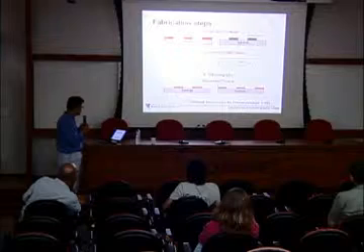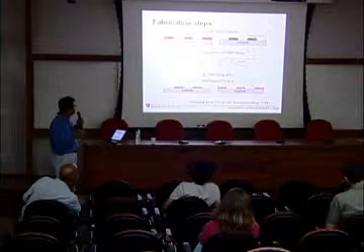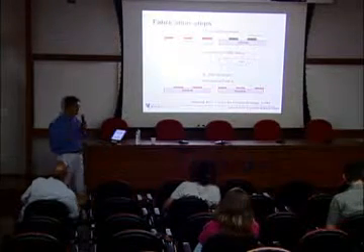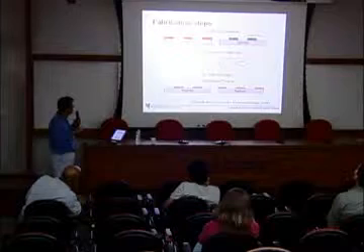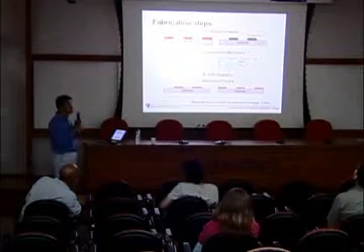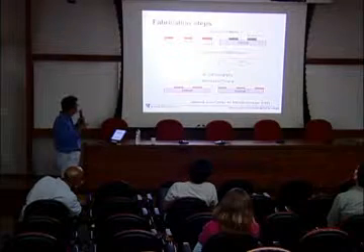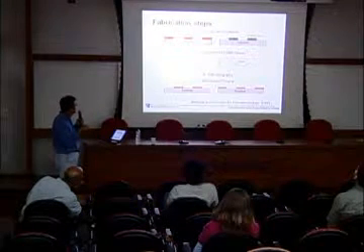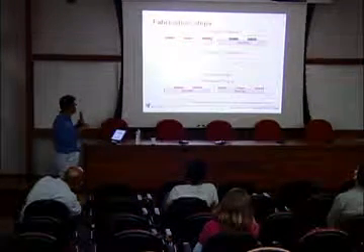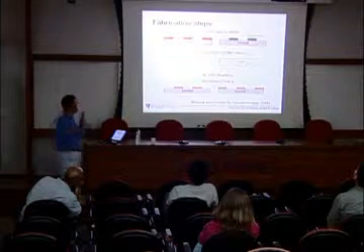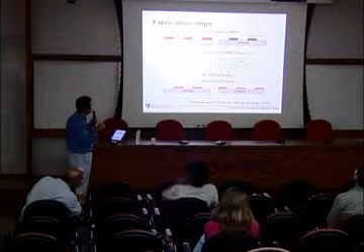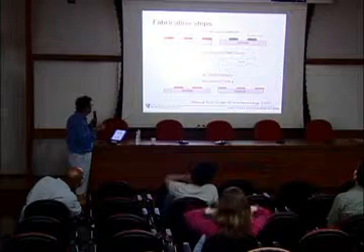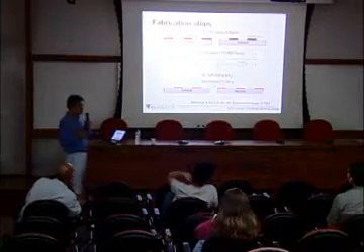And for this soft lithography, we are using a rubber, an elastomer. It's very simple. We have an elastomer, and then we need to make a specific shape. Then we need a mold. Mold means on a silicon wafer, we can use a photoresist as a structure, or this silicon can be patterned to make a specific shape.